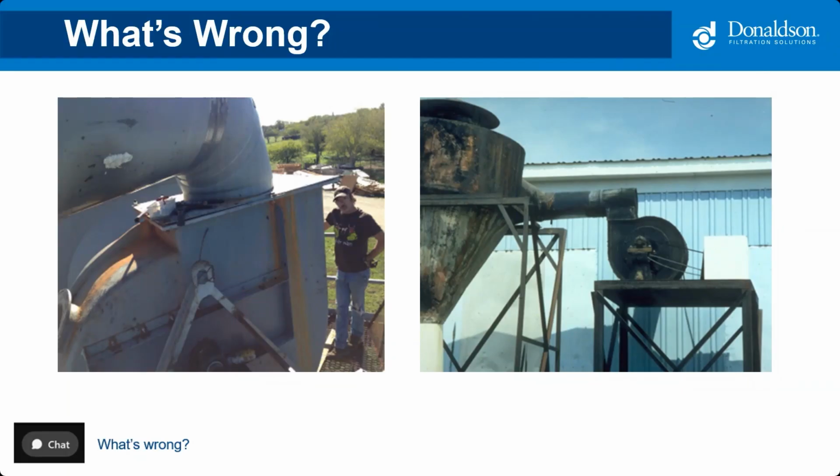Right on. But the obvious one is, I guess the guy's proud of his work there on the left, but didn't have the material to do a nice transition to the round duct. So we'll just stick the very small round duct right directly to the outlet of the fan. A horrible design. We're going to have significant losses on that one.